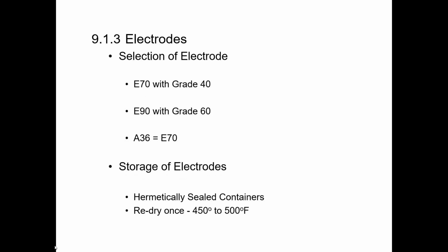I guess I'll stop there to see if there were any questions on what we've covered so far for welding before we keep going. We have a couple of questions that have come in. The first one we have is about table 9.4 for both A615 and A705 or A706. Yes, so that is simply the preheat requirements for welding rebar, whether it's 615 or 706.